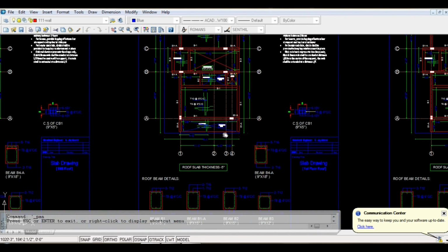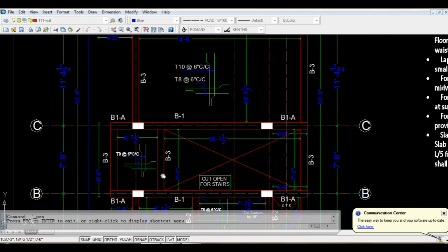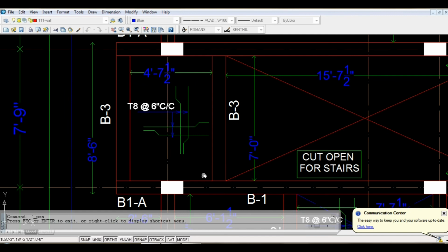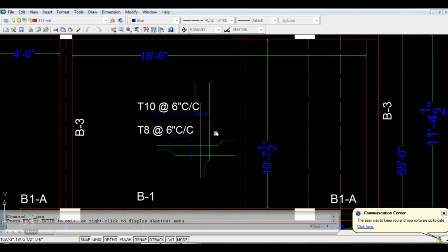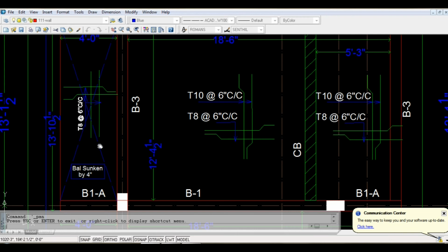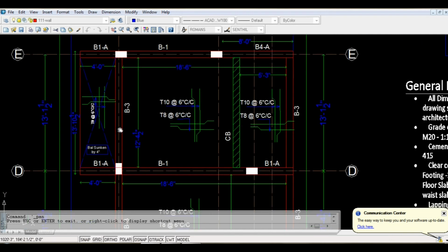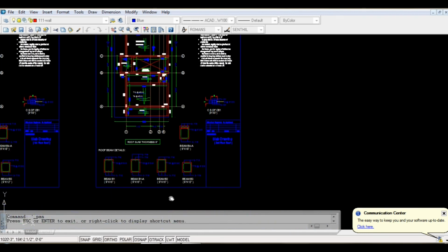Likewise, your other floor slabs also mention the rod details. You see here, if it is both ways 8 mm, it is mentioned as 8 mm rod both ways, or it is given as different dimensions, like 10 as well as 8 is also placed. Wherever a concealed beam is required, it will be marked and highlighted separately. As well, the balcony rods are shown here. So these are the details for the slabs. And let me show you the sample photographs of slab drawings.